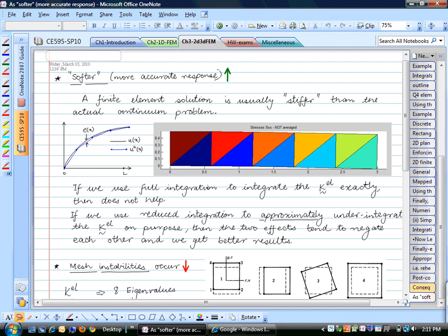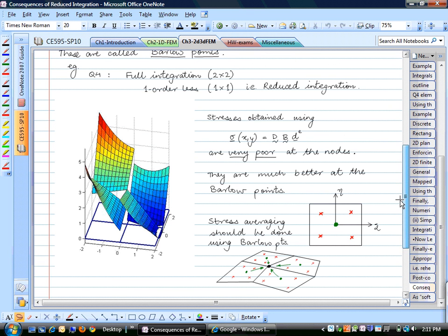And we see that same sort of discontinuity in Q4. So consider this mesh. At the bottom right here, I have 4 quadrilaterals, okay? Let's say I've done my computations, I have found my solution, and now I'm trying to plot my stresses. If you were to calculate your stresses with this formula and plot them exactly everywhere over the entire element, you would see that at the edges of the element, you would have discontinuities in stresses.